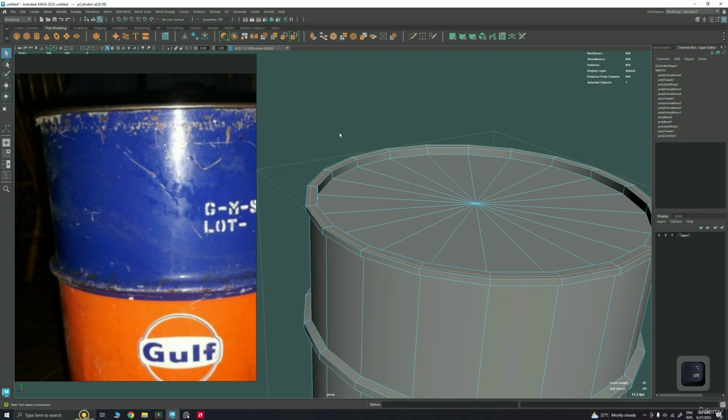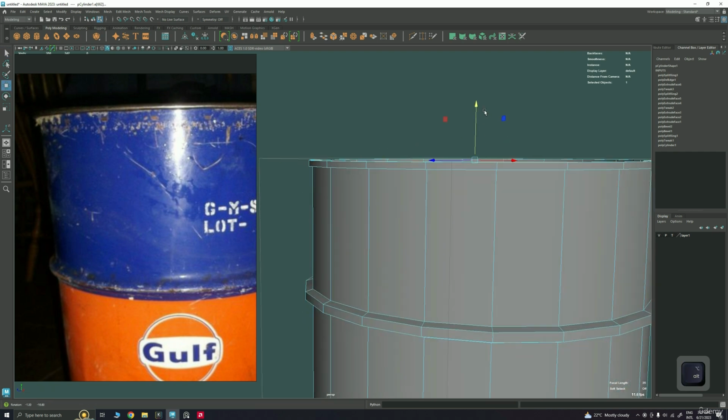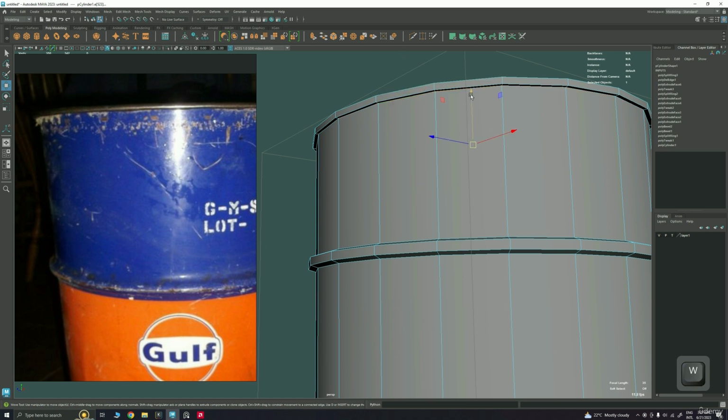What you have to do is hold shift right mouse button and hover over this delete edge button and let go of your right mouse button. And again we are going to split this edge exactly in between, and to do that, you know what we have to do. Select this edge, hold Control, right mouse button, edge ring utilities, and to edge ring and split. Okay. Let's bring this edge a little up, and let's bring this edge a little down.